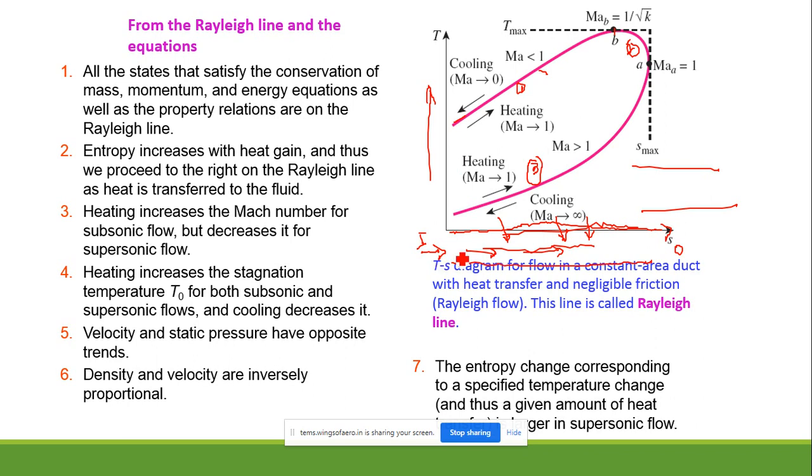Then if a supersonic flow is passed inside the duct, first of all, my condition is that a subsonic flow is passed. While passing a subsonic flow and adding heat, automatically the velocity of the flow gas will get increased, up to Mach equal to 1.